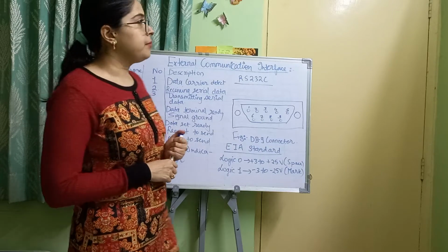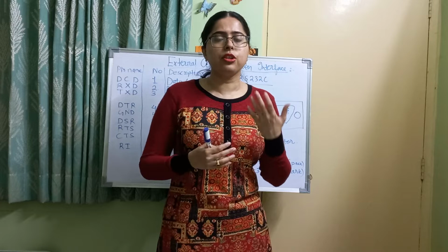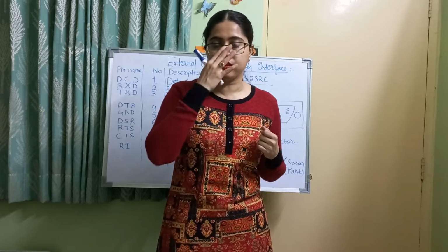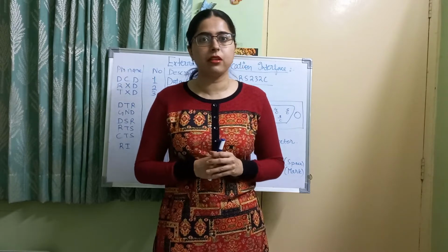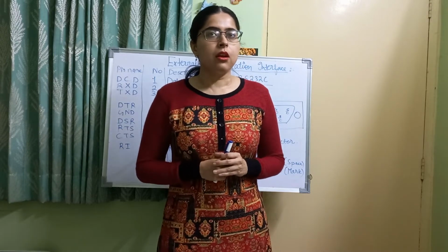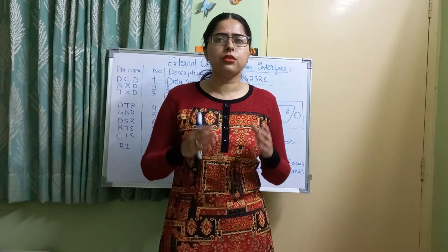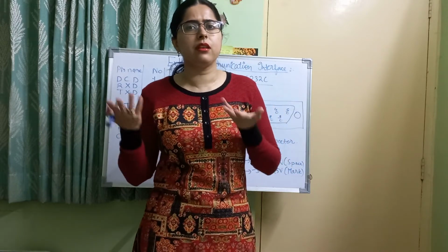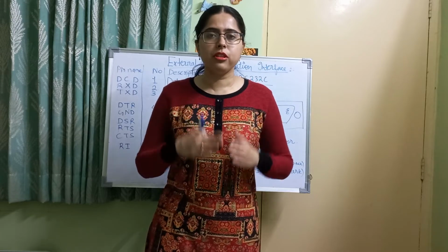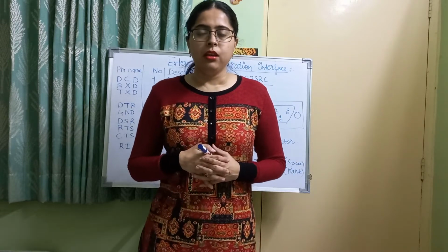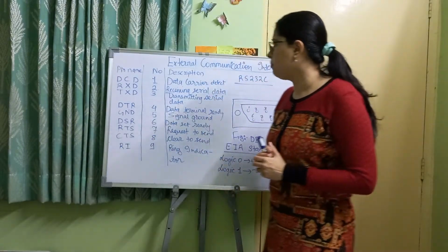Fine. And now our DB9 connector or RS-232C connector has a total of 9 pins. It supports two types of connectors, DB9 and DB25. In this class we are going to study the DB9 connector. Now the question arises, where is this DB9 connector used? See, it is not used much because of USB and modern communication techniques, which have pushed down RS-232, but it is used in legacy industrial applications. Okay. So one by one we will study the pins of this DB9 connector.